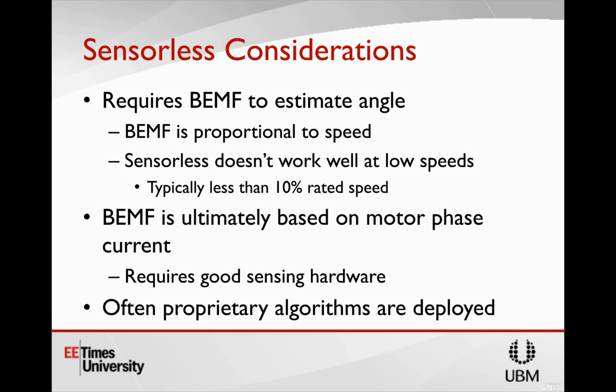One of the things that often happens is that there are a lot of proprietary algorithms out there, often provided by MCU manufacturers who have spent research to differentiate their product by having a unique offering in the sensorless space. So we've talked a little bit about sensorless when you're actually running. But we have some of the same considerations we talked about yesterday with trapezoidal 6-step, with actually doing the startup of the motor when you're doing sensorless.